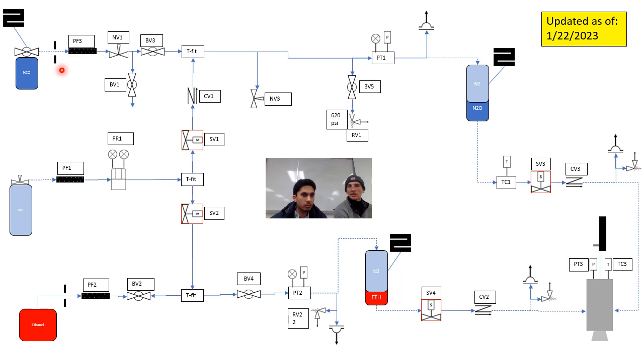We want to recognize that this is definitely one of the more dangerous parts, because you will be next to a pipe that is an oxidizer at 900 psi. So this is the part where we're most careful. I want to think about these processes as best as possible, so they're definitely open to iteration that increases our safety.